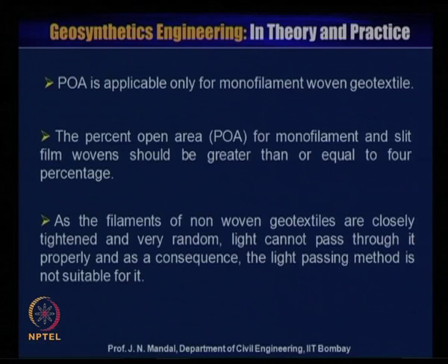As the filaments of non-woven geotextile are closely tightened and very random, light cannot pass through it properly, and as a consequence, the light passing method is not suitable for it. So it is preferable to perform the test for woven geotextile rather than non-woven geotextile material.